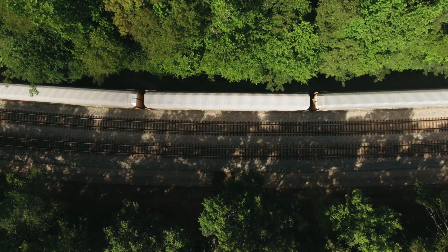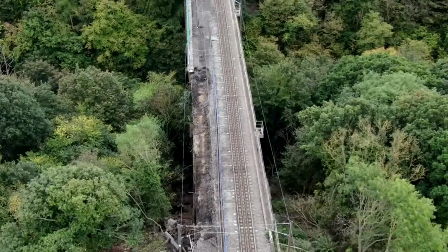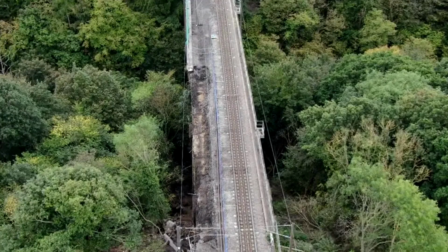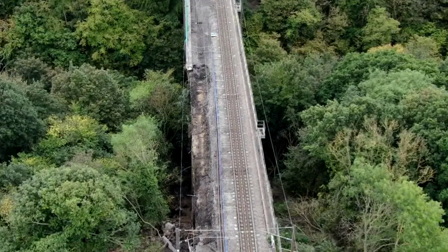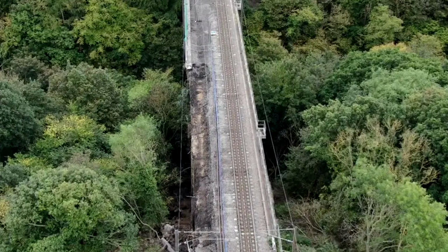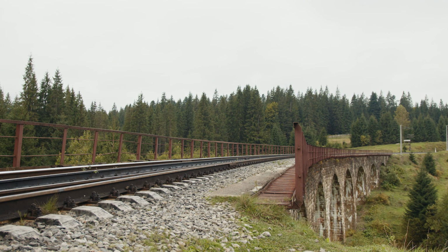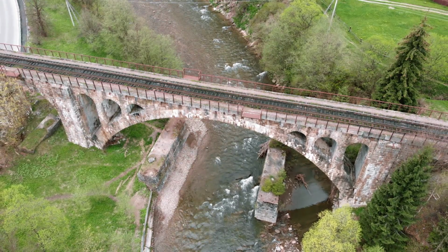You might need approach slabs to spread the stiffness, GSLs or polymer treatments to create a gradual transition of stiffness between track and structure, controlled lifting regimes that don't overload the structure. These aren't just optional extras, they directly reduce fault reoccurrence. Failure to design the transition properly, and it will become a fault hotspot for years.